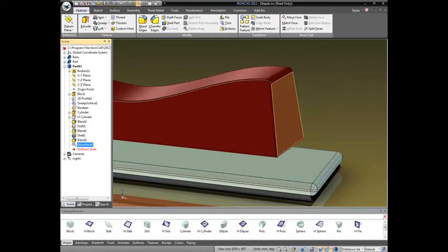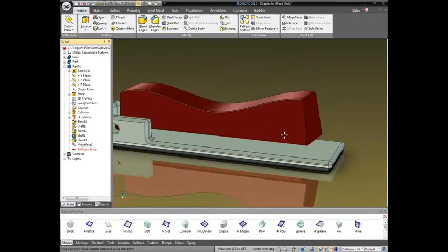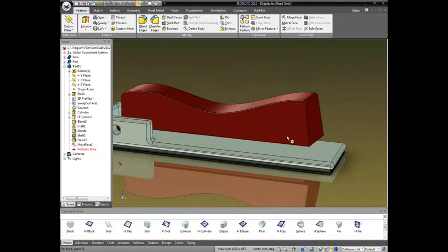new feature down here. Rather than compressing the local operation or the other features in it, it just creates a new feature. So you can actually roll back from that and see the difference. Play back to the end. So that gives you more of a SolidWorks type methodology. Rather than just moving the face and compressing down the shapes, it's creating another feature, which is a unique advantage.